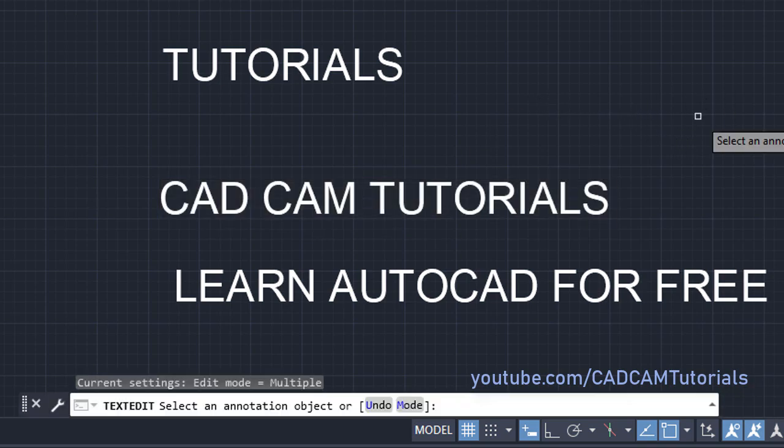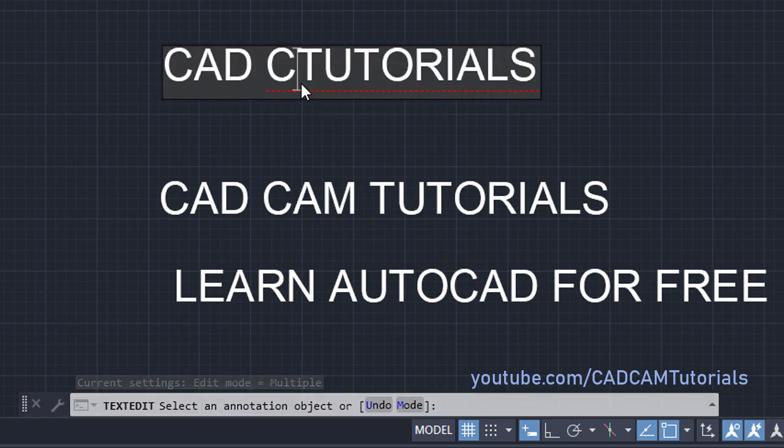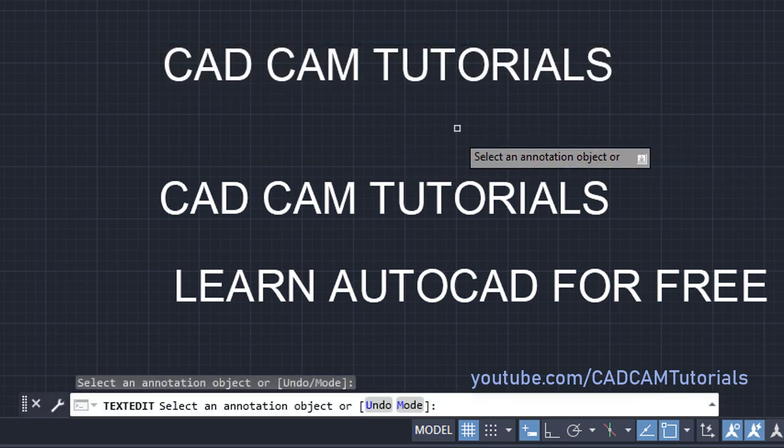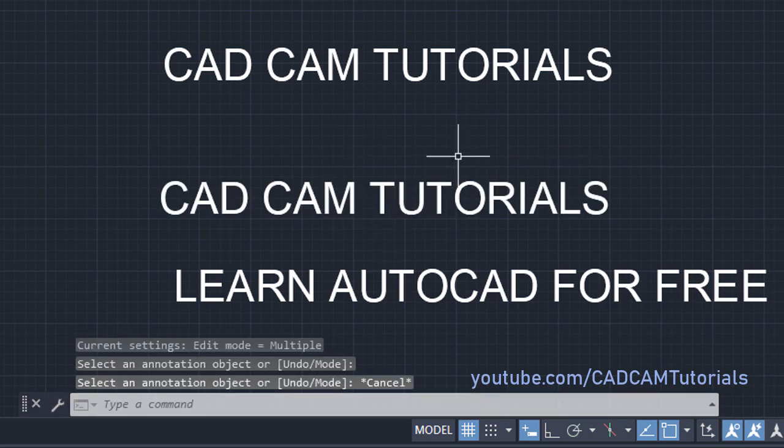Then click outside. Now the text edit command is still running. If you click on another object, you can edit it also. Suppose here again I want to write CAD-CAM space, click outside. Once your editing is done, you will have to press escape. So in this way you can edit by double clicking.